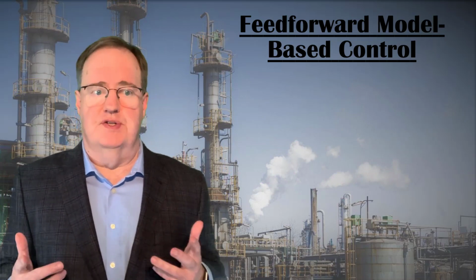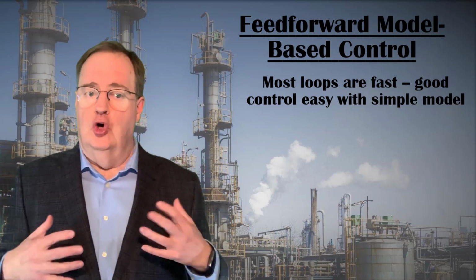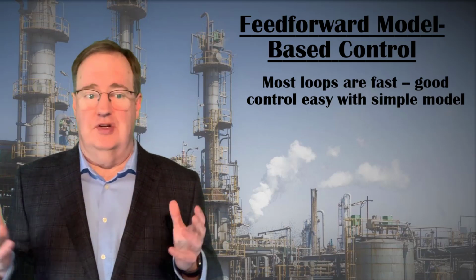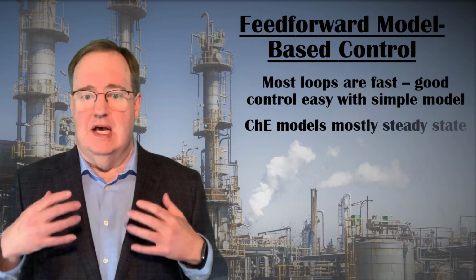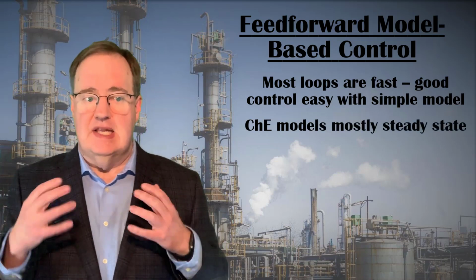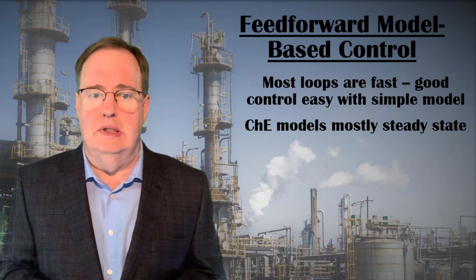There are several reasons for this. For simple, fast feedback loops like flow, pressure, or the temperature leaving a heat exchanger, a basic knowledge of dynamics is quite sufficient for excellent control. Second, we design processes largely with steady-state models. Steady-state models don't describe everything we need for dynamic control.